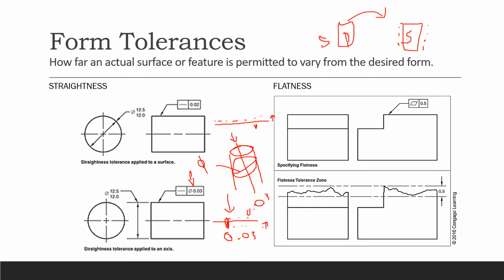So therefore, the straightness got to be within this. This picture is so exaggerated, so it looks like your axis is so big. It's not like your axis is a real small line. And this is a very tiny little diameter, a very small circle that we're drawing in an exaggerated way. So anyway, you got the idea. But your straightness can be like this. So this is over the circle, so your axis is too big, because it's beyond the permitted zone right here, which is 0.03. I think you see it now. It takes some time for you to be able to see it, so please take time to see that.